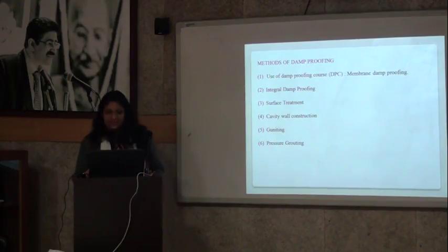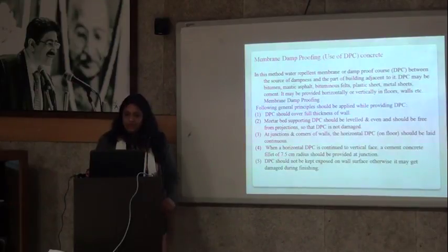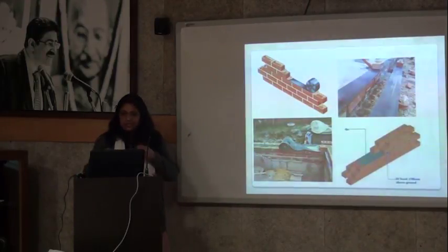Yes, ma'am. This is membrane damp proofing. This is done between the substructure and the superstructure. The DPC level is provided so that the dampness from the soil cannot travel and go up to the superstructure of the walls. So I can show the pics.